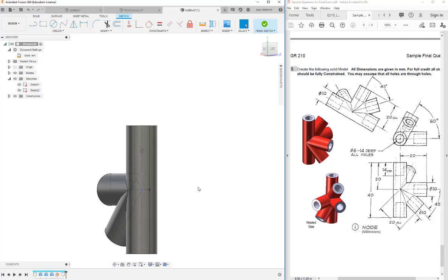So I'm going to go ahead and look at that sketch. And what I'm going to do is I need to make a horizontal tube, so I can use the rectangle for that, and then a tube at an angle at another 45-degree angle. So clicking on that origin, and then that's dimension of 20. This is dimension of 5, just like we have done before. And then I'm going to use my line tool just in a similar manner that we did before.